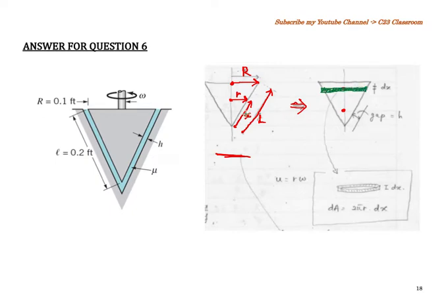We assume that the axis of x here is similar to this thickness because the inclination is very small, so we assume that the distance of this one is also equal to x, meaning a small portion in the x direction. And then this is the gap between these two moving and fixed surfaces, so it is equal to h here.